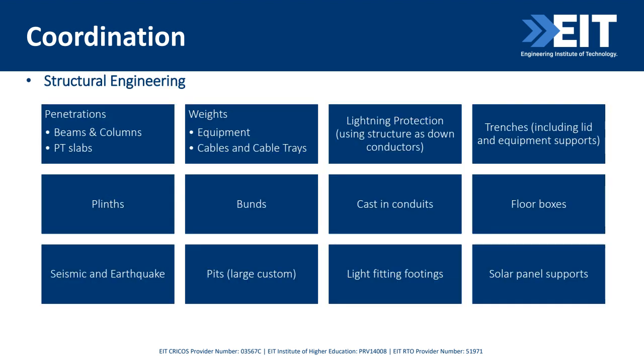Structural. Anything from penetrations such as cable risers, or if we've got any equipment that's very heavy. Lightning protection is probably the biggest coordination piece we do with structures because we often use the structure for our design. They help us with our trenches, providing us plinths for our boards or bunds for our generators.